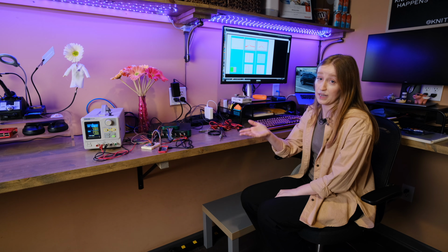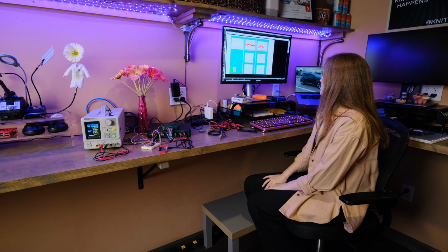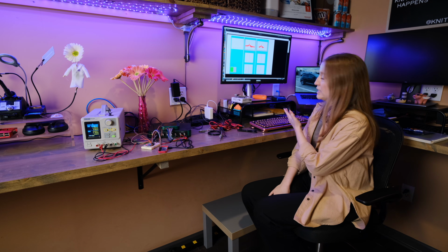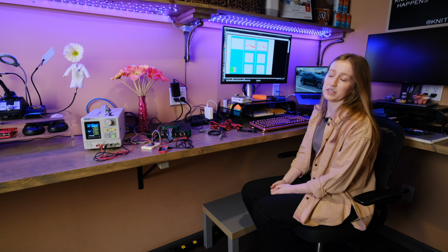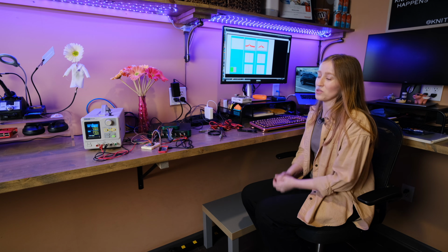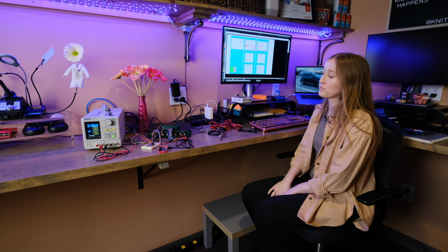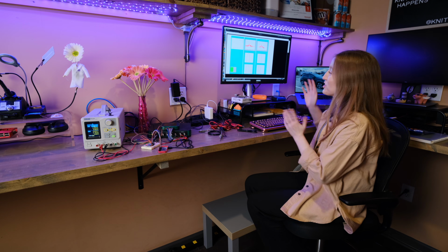However, the circuit's design has good ESD protection, but only so much so. I'm still at 800 on my center frequency peak hold here. I'm still only at 865 kilohertz instead of my 1 megahertz. So obviously this would not be an acceptable device to use in any endpoint application, but you can see how my test setup has told me as such.